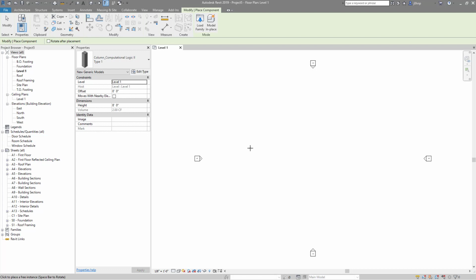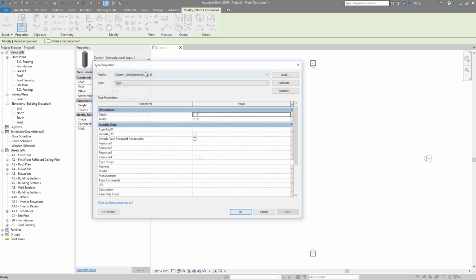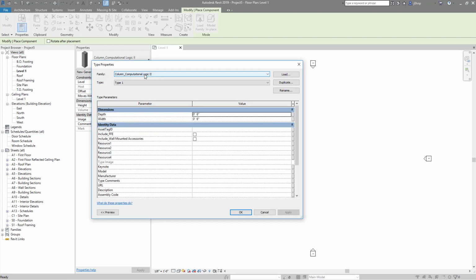Back in the Revit project, we are now in a Family Instance Placement mode. We can utilize this mode to view the type parameters of this family. Let's click on Edit Type in the Properties dialog. Within the Edit Type dialog, we can notice that we still have the 3 same types loaded into this project. Navigating between each type, we can see in the Dimensions category that we have a unique depth and width parameter as type parameters. And we can see that that's reflected in each of the types.